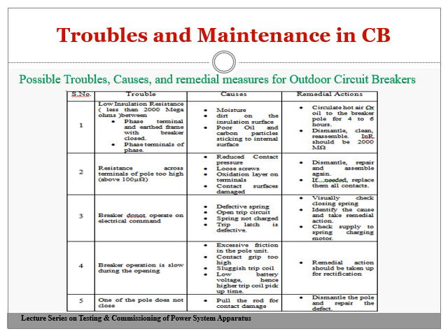This is the resistance that exists between two conducting terminals separated by an insulation. Therefore, here a low value of insulation resistance means deterioration of insulation, the same meaning as you have dealt with in all the other modules. The insulation resistance reduction is due to the absorption of moisture content or dirt on the insulation surface, poor oil, and carbon particles sticking to the internal surface.